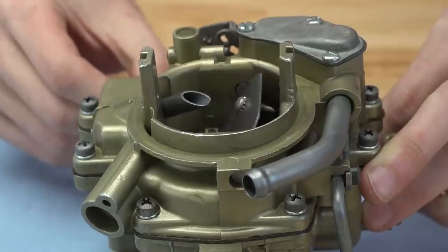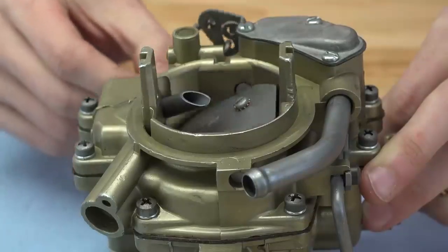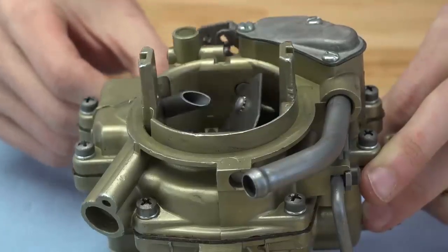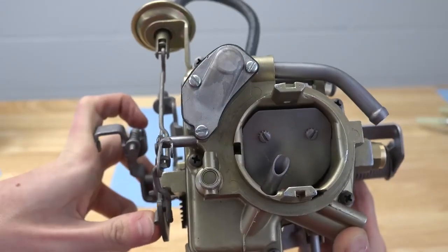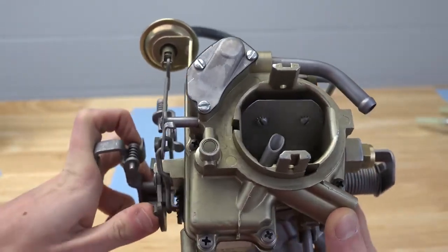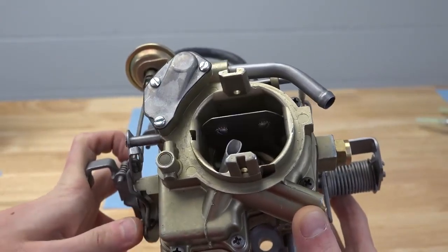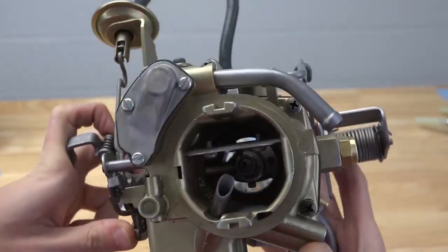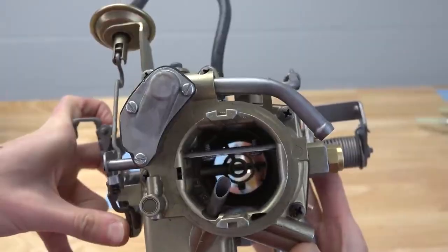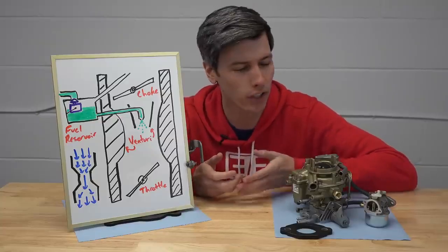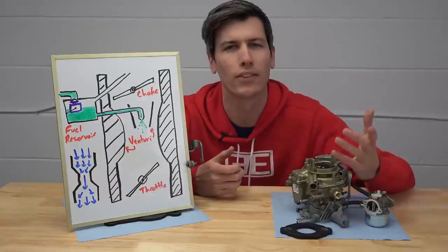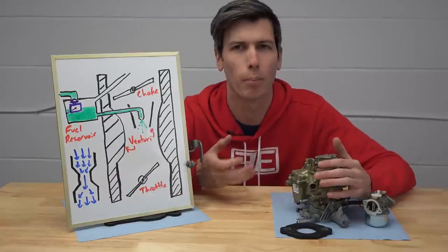And because your engine is cold, you need more fuel than usual because not all of that fuel vaporizes to help start the engine. So you inject more fuel so that you have some of that fuel vaporize so that you can get the engine going. And then once things start to warm up, you can open up that choke completely and the engine runs like normal. So the beauty of a carburetor is its mechanical simplicity. It sees more air going into the engine, so it injects more fuel. So let's say you were to modify your engine so that it's now better breathing.